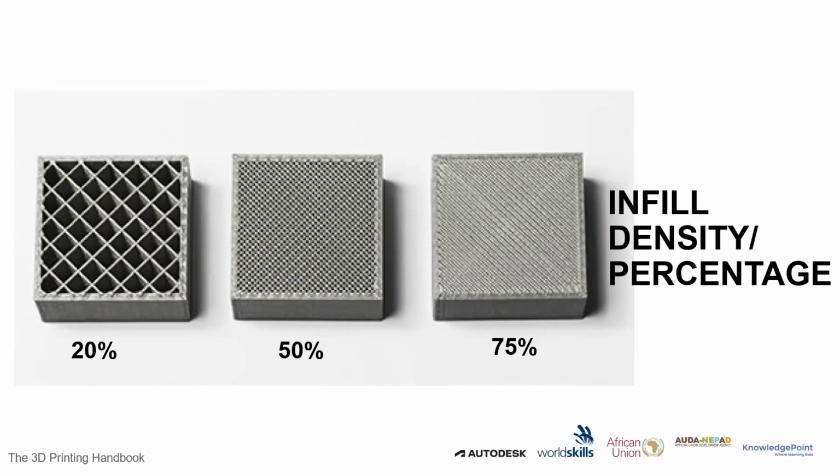So FFF printing really does not have a fully solid inside. Externally, you have the shells, and inside those shells is the infill. The default infill percentage on most printers is between 15% and 25%, with 20% being most common. But when you want something stronger, you want to use a different variation of the infill.